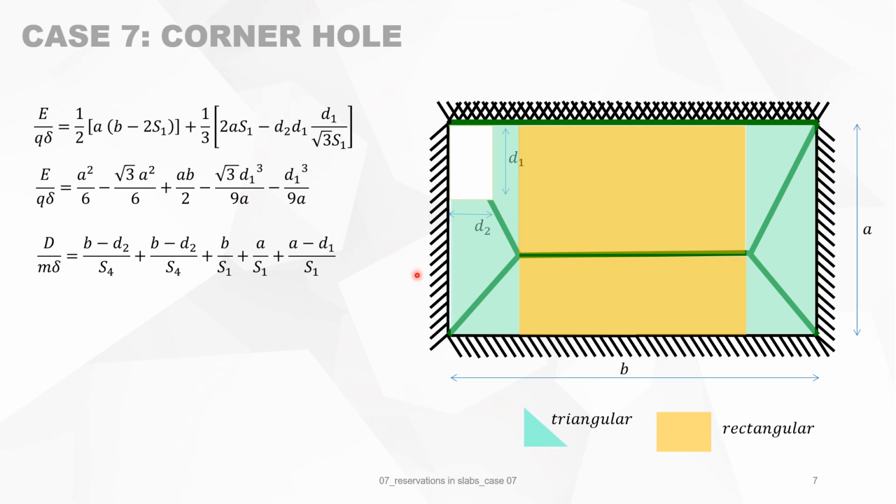Then we look at the work done by the internal forces. We will take the yield lines and project them on their rotation axis. So we have this yield line projected to the rotation axis in the north.